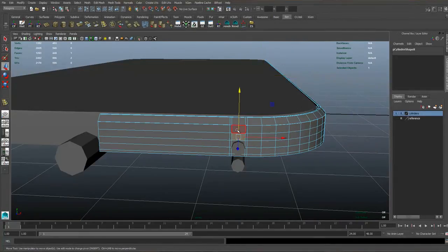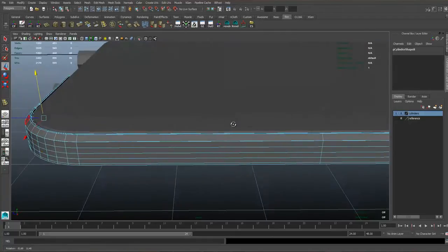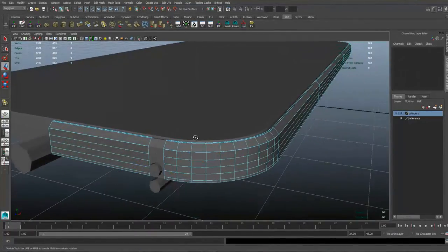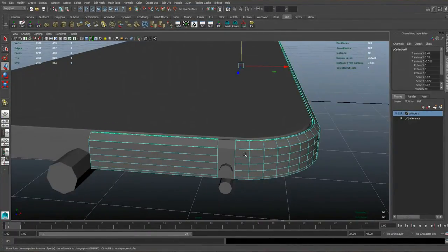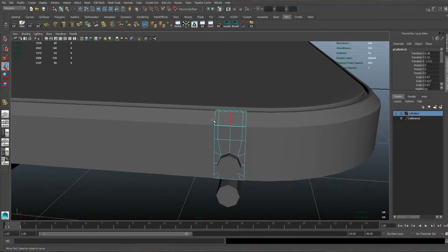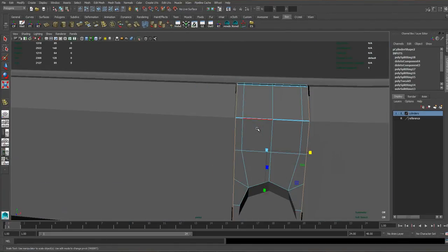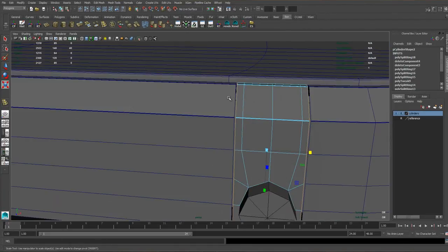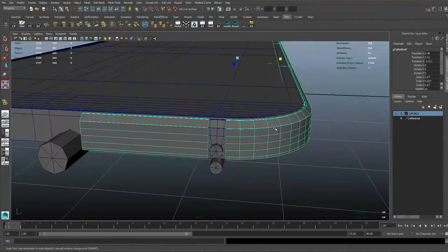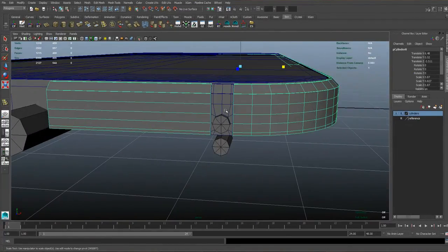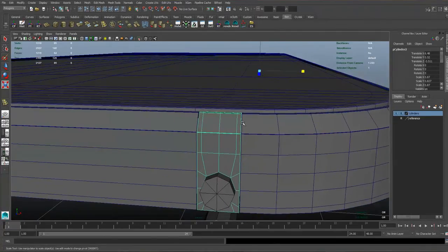I want to do it to this vertical set here, so it's double click, Shift, right, and then hit delete, and it will leave us with the geometry underneath there, which I am just going to get the edges. So I've double clicked on the edges for it, and I'm just going to resize them in a bit because I do need a small gap for when we bridge together. So you should have your geometry like this, and then this piece is separate.